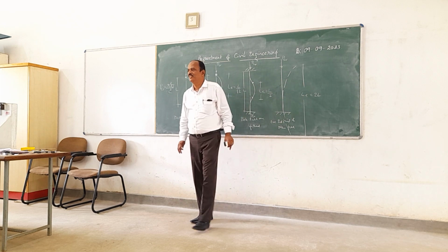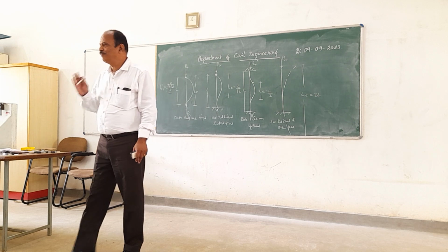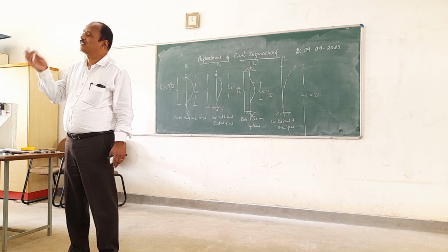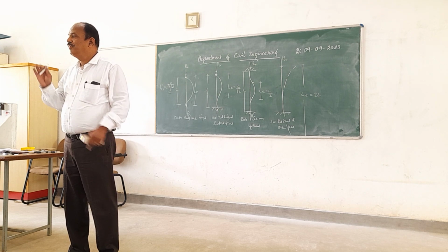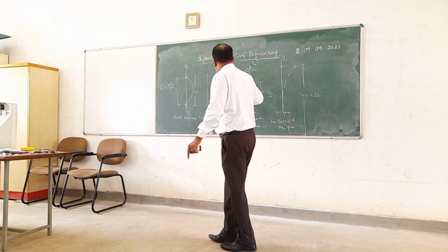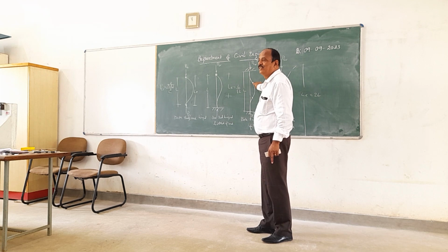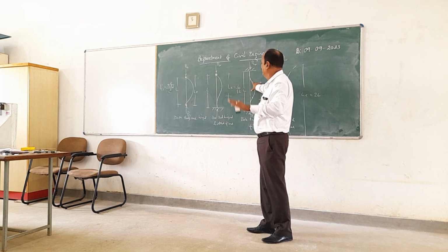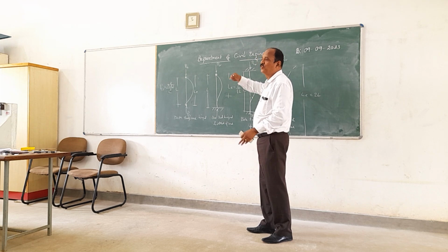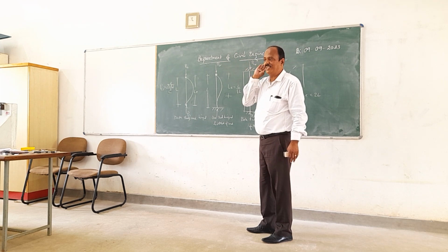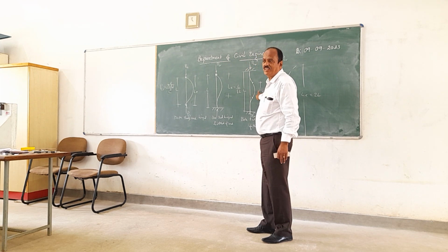Then what is this effective length? The effective length of the column is nothing but that particular length for a column made up of the same material, with the same hinge conditions. If you take up this particular length, the load we are going to apply, we are going to get it for the column. With the same load, same material E, if you measure that critical load in the actual column, it remains the same. That length, in general, we call the effective length.